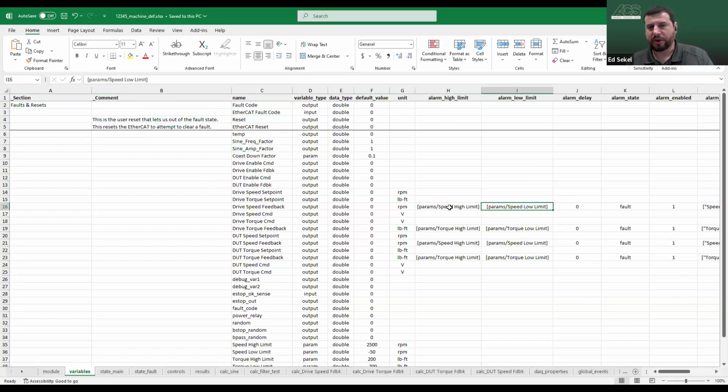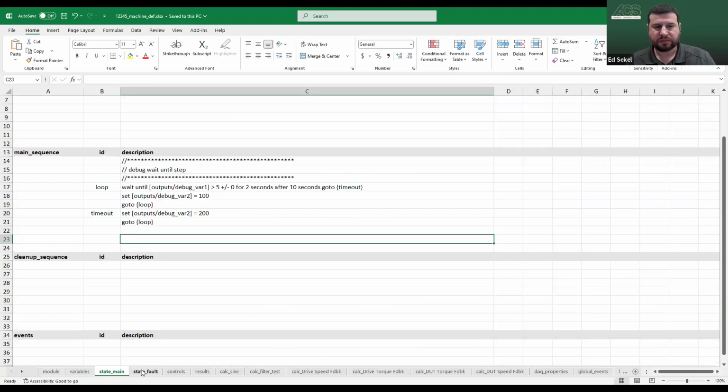And with the alarm parameters, if it goes outside of the alarm, you can configure it to execute a certain state, which is another defined script that would cause the system to perform a certain action. And all of this will be executed down on the real-time side. So you're achieving a deterministic control and execution while this is being processed.